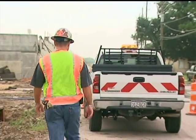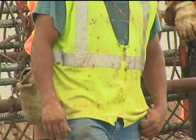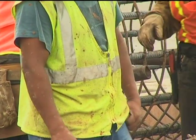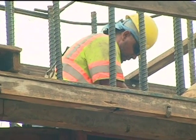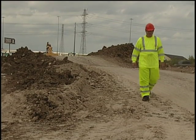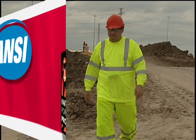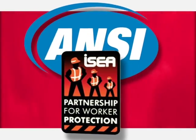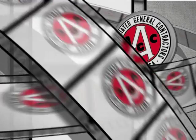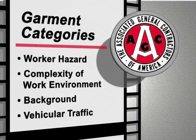When working in road construction zones, always wear high visibility safety apparel with or made of reflectorized or high visibility material so that you can be seen by other drivers or heavy equipment operators. This apparel includes high visibility headwear, vests, jackets, coveralls, trousers, and harnesses. The American National Standards Institute and International Safety Equipment Association define 3 garment categories which are based on worker hazards and tasks, complexity of the work environment, background, and vehicular traffic.